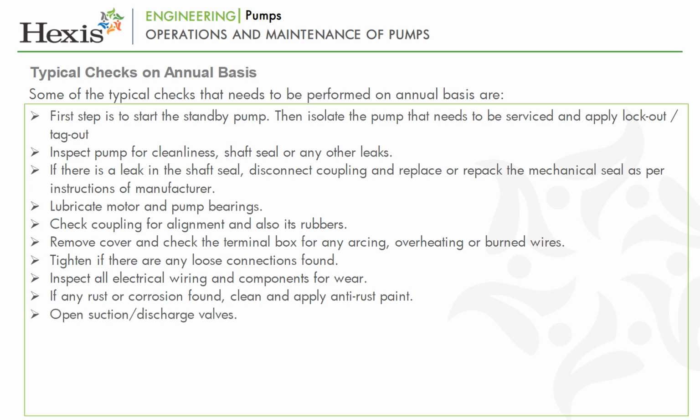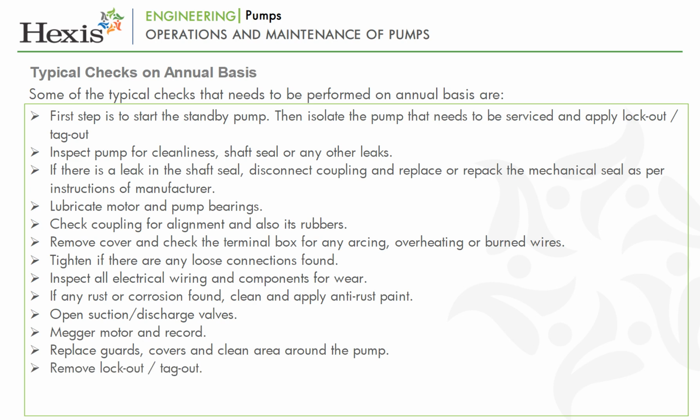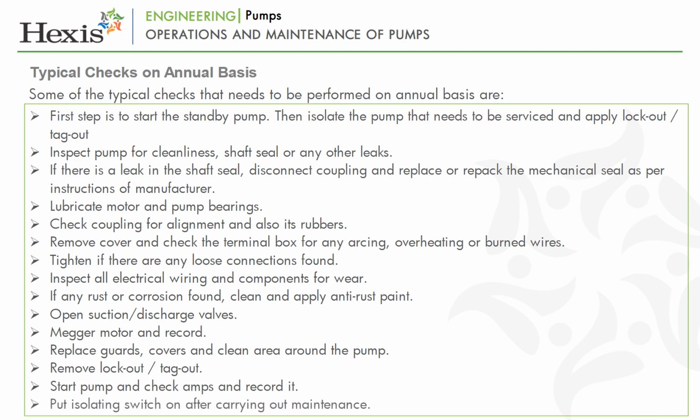Open suction or discharge valves. Measure motor and record. Replace guards, covers and clean area around the pump. Remove lockout or tagout. Start pump and check amperes and record it. Put isolating switch on after carrying out maintenance.